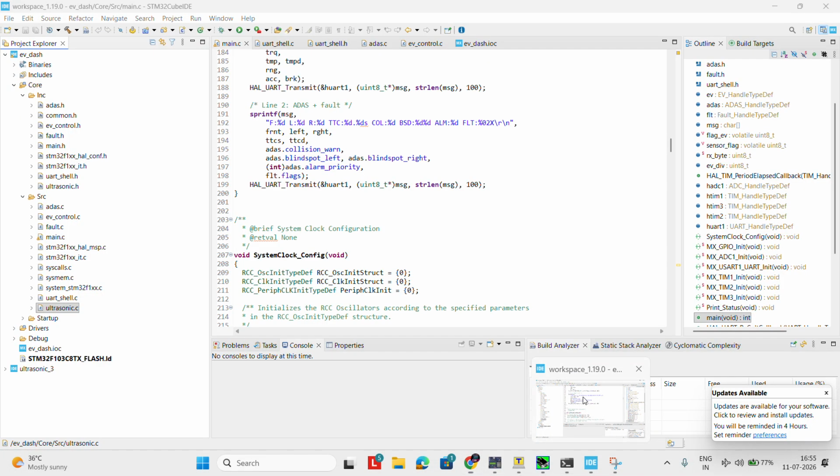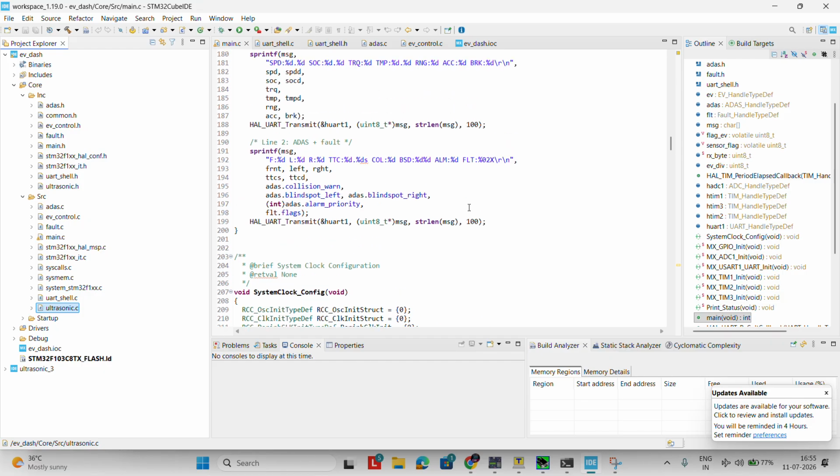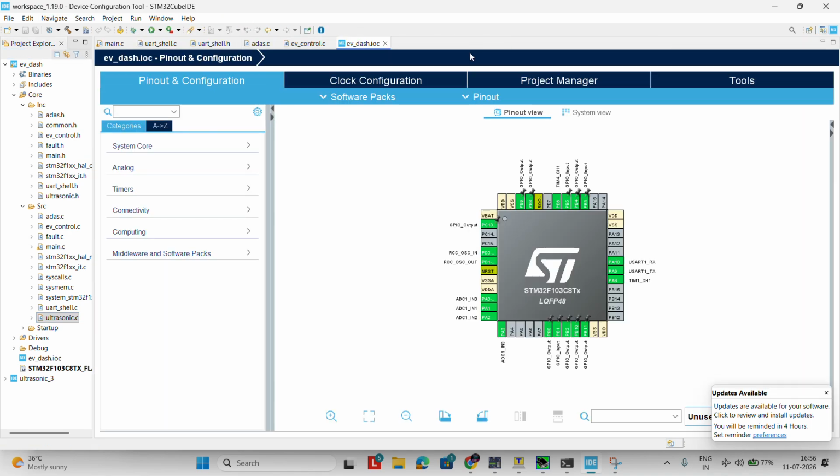So first we'll go to STM32. Over here, see, STM32CubeIDE is the brain of our project, right? So the initial phase includes configuring the IO pins. You can see PB8, 9, 10 and so on are LEDs. This is UART1 for transmission and receiving. This is for transmitting the calculated data to the Python dashboard at 115200 bits per second.